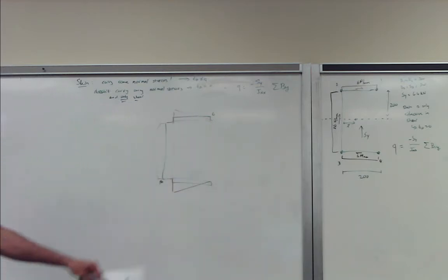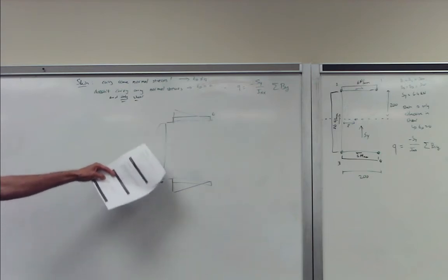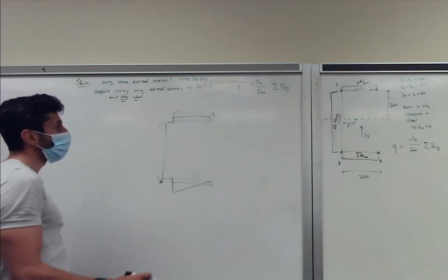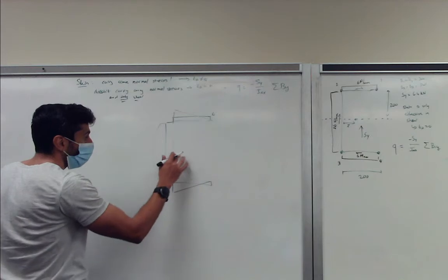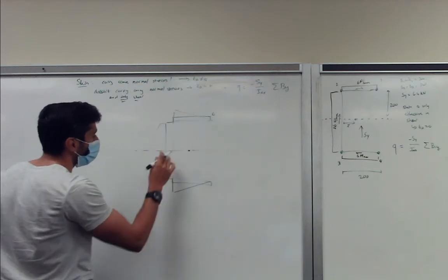So the shear flow would linearly increase in the bottom and top flange, and will be quadratic on our vertical flange. So yes, we made our life easier, but it also came at a cost: we lose accuracy in our solution. If you calculate the maximum shear flow for our second case, we always know that's located somewhere in the centroid.